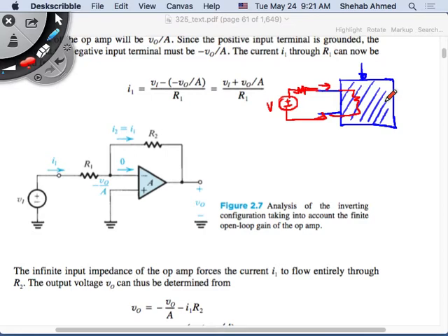If you draw a little bit of current, and these two devices are in the same parallel branch, so if you have a resistor here with current flowing through it, and I put another one in parallel here, then some current will flow in here as well, but the voltage across these two is the same. So this is like a voltmeter. But you don't want to draw too much current because then you're going to affect your circuit. So this is a voltmeter.